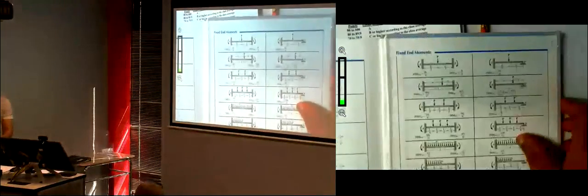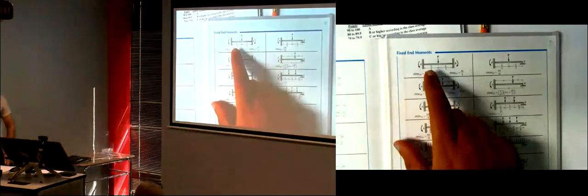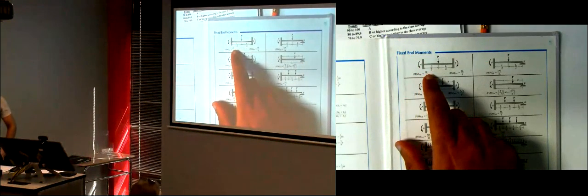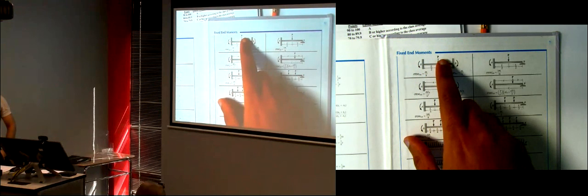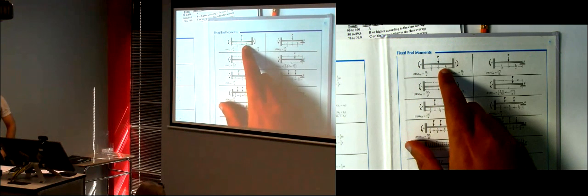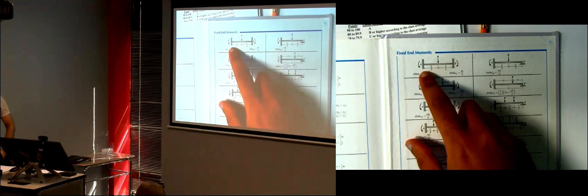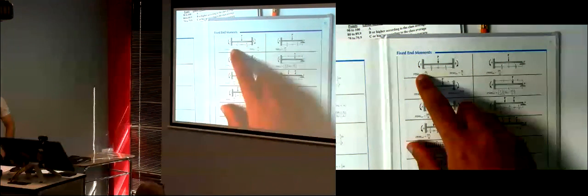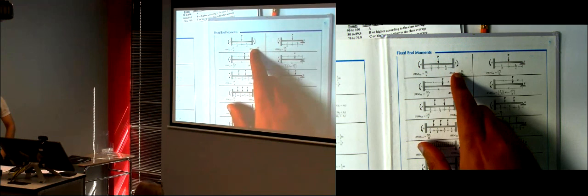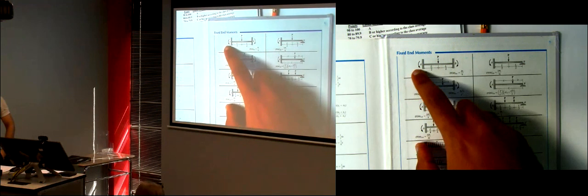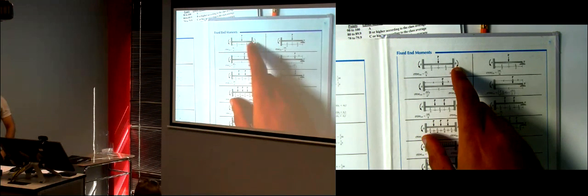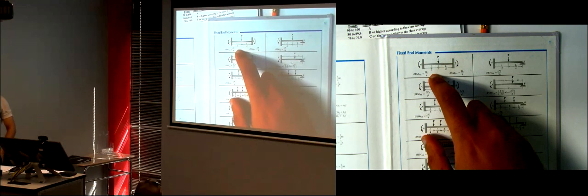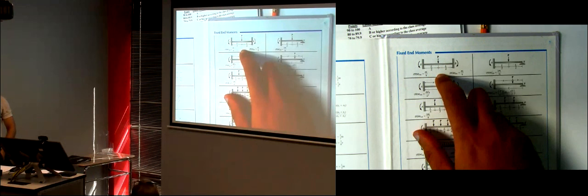So this is the back of your book, the fixed end moments. This is what we derived today. Okay? A member with just a concentrated force right in the middle of the length. L is the length of the member. You find that the fixed end moment here is equal to the same magnitude as the fixed end moment here. It's PL over 8, and you're given the direction here of those fixed end moments. Okay? If you don't want to memorize it, it's given here. Okay? On the test, I will give it to you if you didn't memorize it.